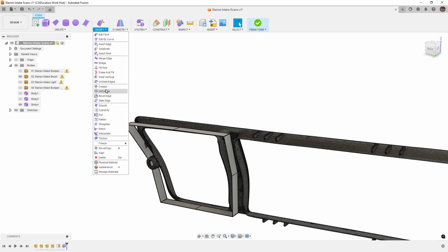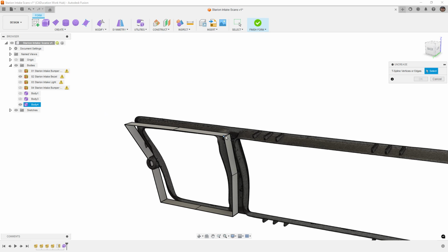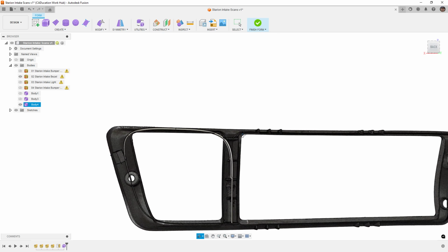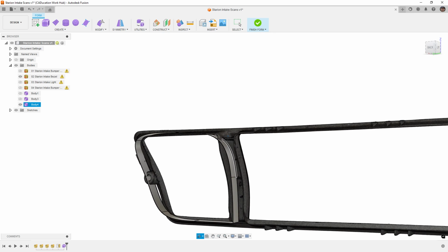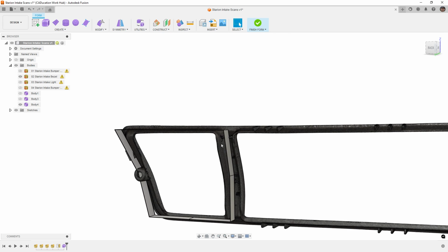The next step for me is I'm going to go into the crease uncrease tool, and I'm going to uncrease all the edges. It's not going to look very different right now until we go back into smooth display, which is Alt and 3. And you can start to see that with smooth display, it doesn't match very well. It looks like I need to uncrease this one as well. So uncrease. But if we go back and forth into box display, the box display still represents it.